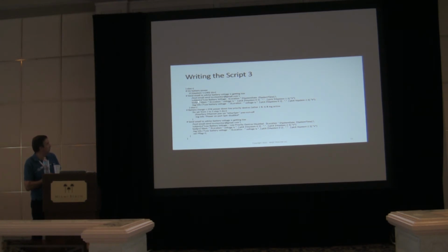Yeah, sorry, let's start on that. The subject on the email would be low battery voltage. It will tell you the location, the date and the time. And then the body of the message would tell you alert, the location, the voltage is, and this here is picking up the first 2 digits of the voltage, putting a period between them, putting another digit for you, putting a space, and then putting a V. So it will look like 24.8 volts when you read it. So that's all that's doing, is putting together a string of variables so that it reads sense for you in the email when you see it.